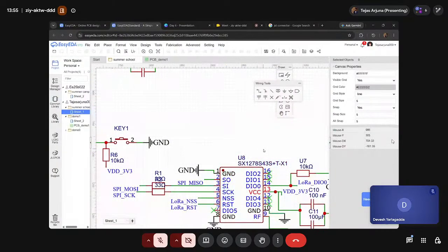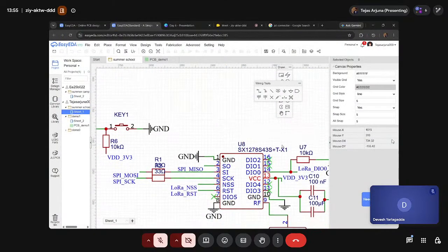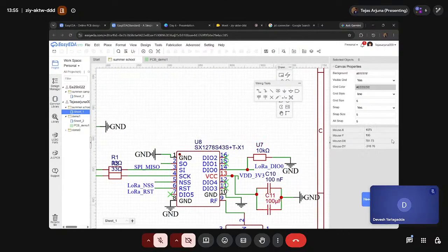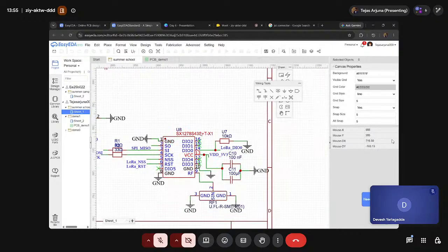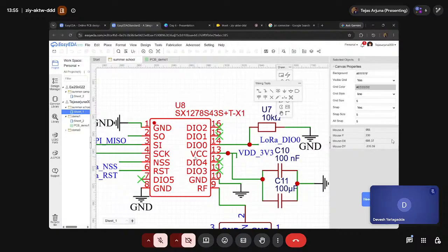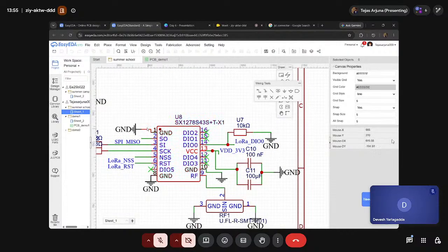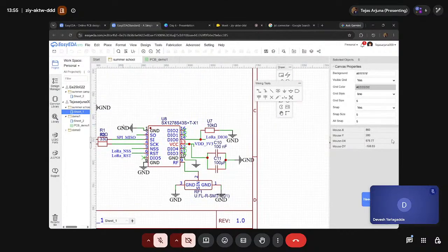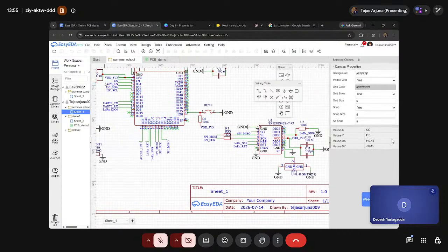So let's say the VCC, always remember, and even if you use traces, PCB layout or not, current flows in a closed loop. So the VCC of this part will get its power from the VDD of the ESP32 or directly from the regulator, and it goes into this VCC and circulates through the internal circuit, providing current, and then comes out through the ground, and the ground will be connected to the ESP32 ground or to the regulator directly.